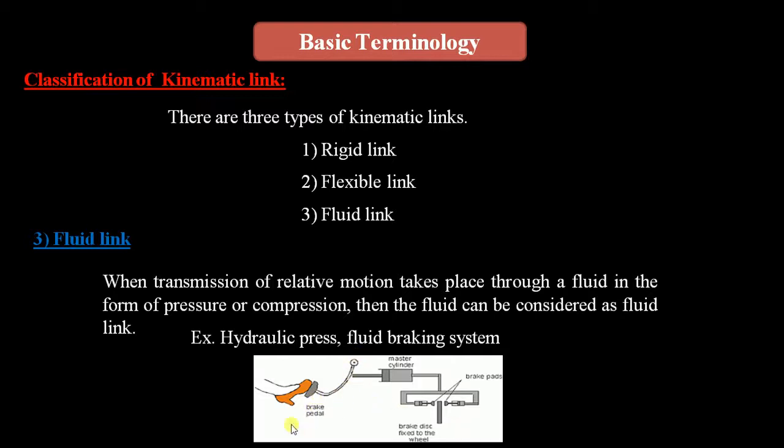Here, when you look at the operation, when you push this brake pedal about this pin joint or pivoted joint, this rod will push the piston inside the cylinder. This cylinder is entirely filled with liquid, assume any liquid, not particularly water. So whenever you compress it, this fluid will apply force on the two pistons arranged in the two small cylinders.